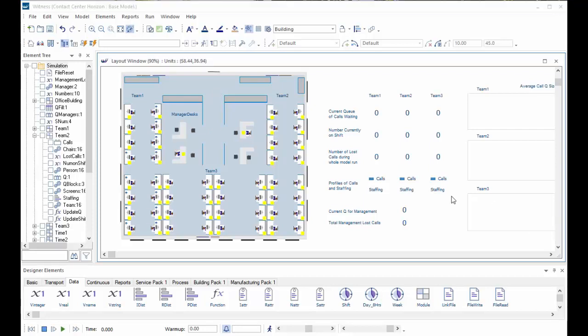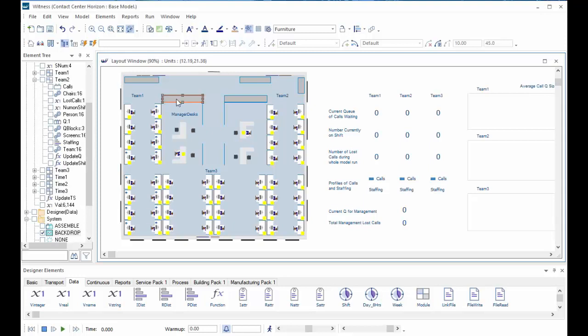Now the next thing we'll move on to is the incidental furniture that's been arranged around the building. In a later tutorial we'll cover the chairs and the people and the cubicles, but these rectangles here at the top of the model that I'm highlighting, they are extruded to create benches or cupboards. And also the lines that I'm showing now are extruded to make partitions from simple line drawings.